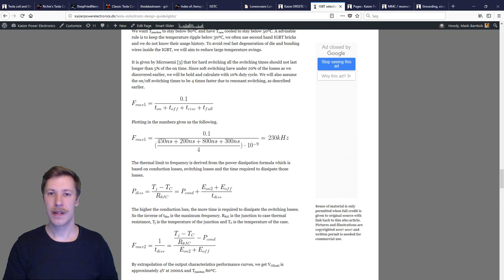Because if we have a too high temperature rise, the IGBT with its thermal impedance cannot cool down between the individual pulses. So we will get a quickly rising temperature. Then it's suddenly 55, 60, 70, 80, 90, 100. And above 125 degrees, we are running out of headroom in the datasheet. So once we come above this and we keep switching, goodbye silicon. You will either melt it or you will have it explode from thermal runaway and simply conducting too much current.